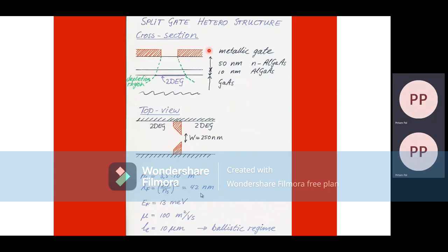Here in the slides, shown in a little more detail once again, on the surface we have the electrostatic gates in red that have been mentioned here, and down below is where the two-dimensional electron gas is found, at the interface of gallium arsenide and aluminum gallium arsenide. However, when negative voltages are applied to these gates, the two-dimensional electron gas is restricted only to this narrow gap that you can see.